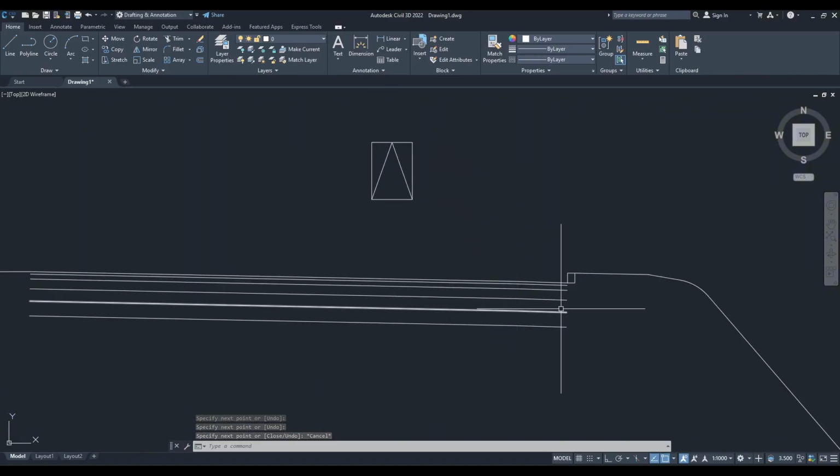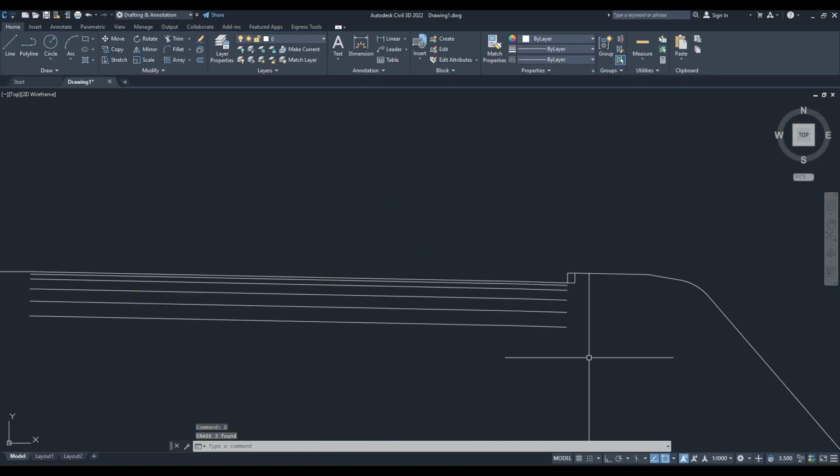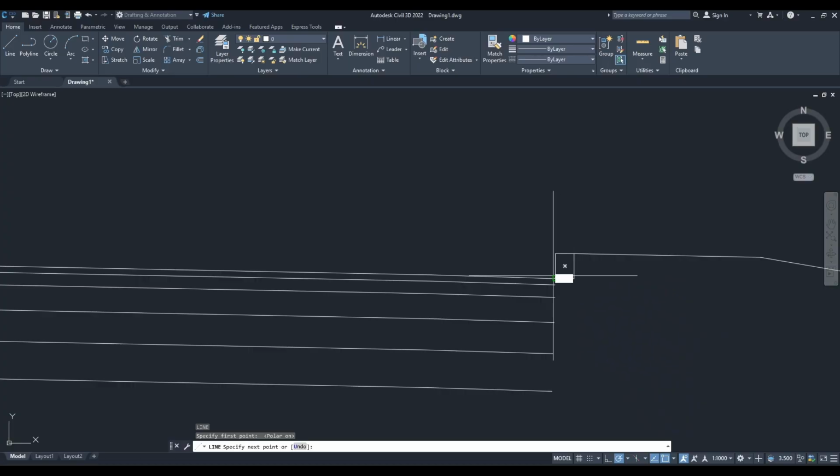For this reason, we're gonna take these layers with the 45-degree angle because they are like sand materials and they will stack like a dune. So for that, take the L command, turn this on, take the 45-degree marker and draw a line of 45 degree